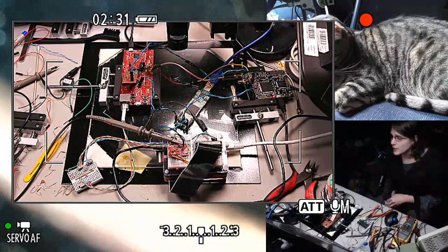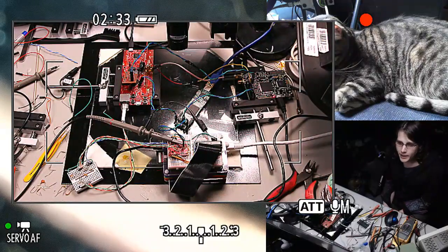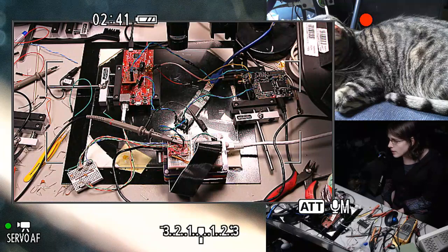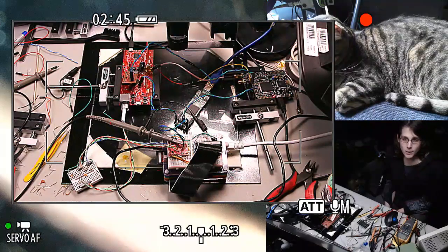And so when I say 30 megahertz, that's the clock that the CPU is running at, but the Ethernet PHY would be running at a 6 1/4 megahertz clock instead of its usual 25 megahertz. That works fine, but below 6 1/4, I would start to have problems that seem like they might be the transformer. So in a previous stream, we took off the transformer on both sides and tried capacitively coupling the two Ethernet PHYs, and it didn't really work by the time I had to end that stream.